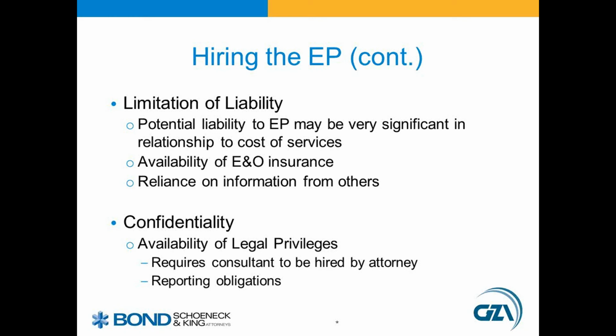There is currently in the petroleum bulk storage regulations, that is 6 NYCRR Section 613.8, entitled Reporting of Spills and Discharges, language that reads that any person with knowledge of a spill, leak, or discharge of petroleum must report the incident to the department within 2 hours of discovery.